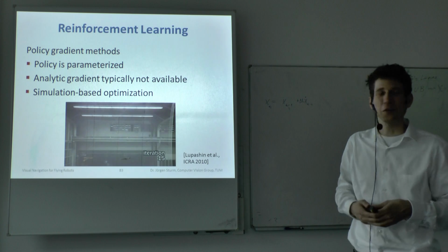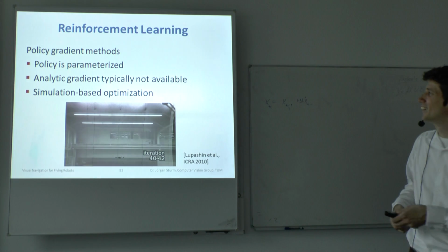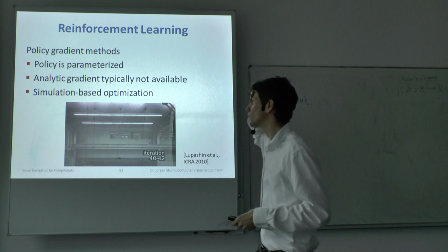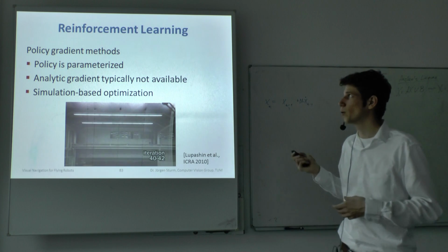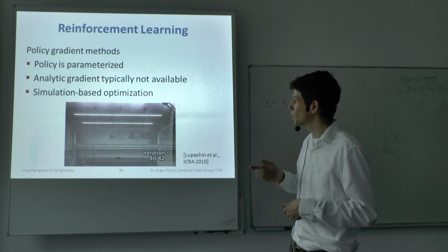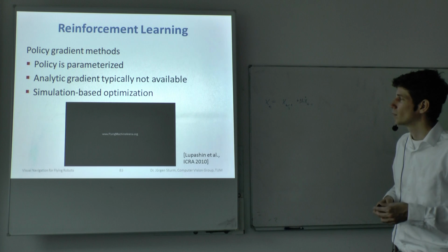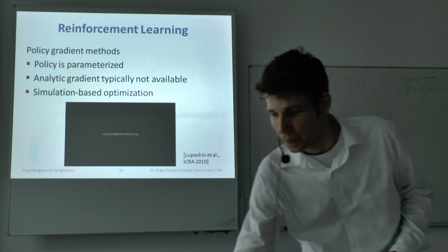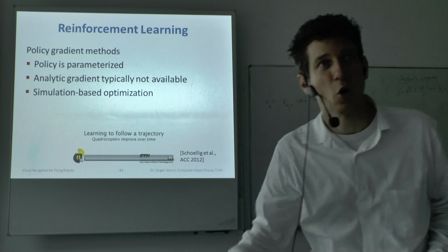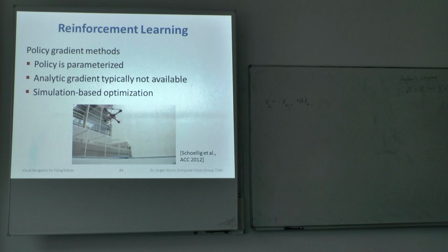So one thing that you can do is to have human learning in the loop, right? You adjust the gains until it does the flips correctly. Or you can have a machine learning technique, the so-called policy gradient methods that iteratively change the controller gains until you end up with the desired behavior. But this is definitely more advanced and not something that you can do in a day or so.